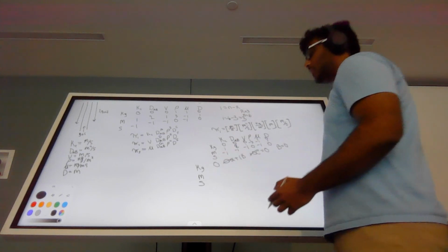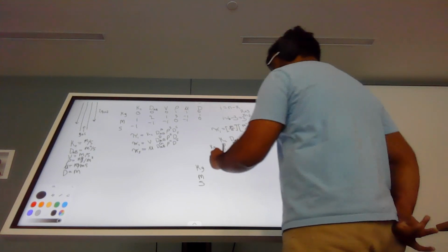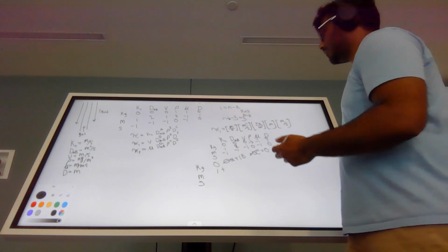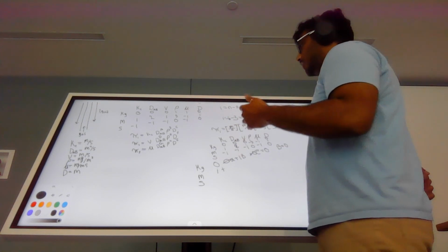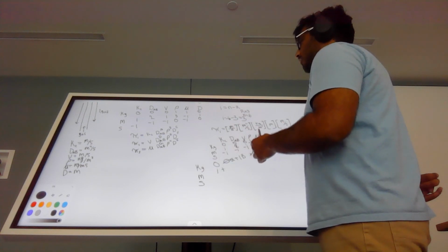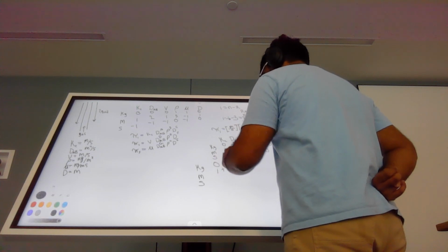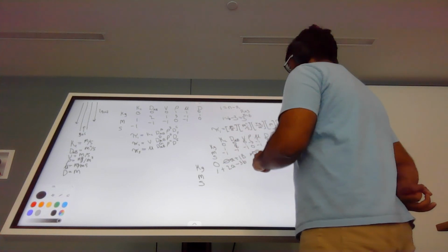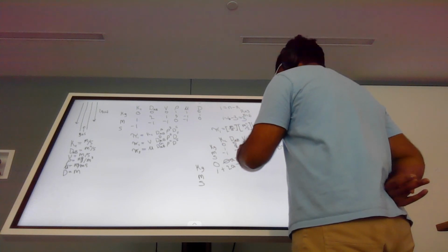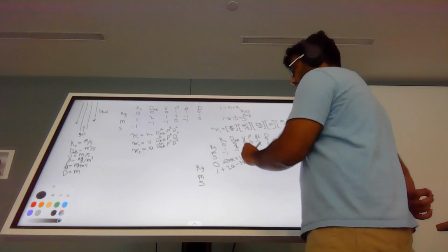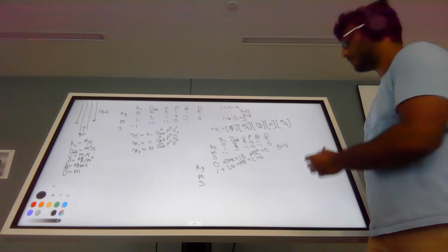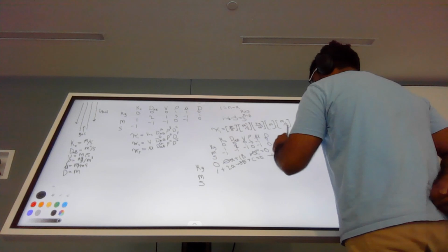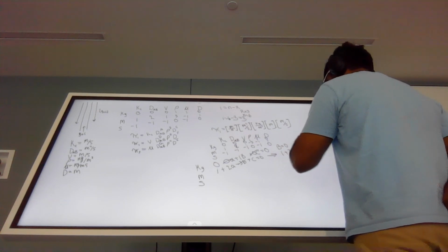So now we're going to analyze the meters within the units. So it's going to be 1, because that's our isolated variable, and we're not raising that to any power within our pi group. So since there's 1 meter in the numerator, we're just going to write 1. And then for our mass diffusivity, it's going to be 2A. And then for our density, it's going to be minus 3B. And then for our diameter, it's going to be plus C equals 0. And we could go ahead and cancel out B because we already knew that B is equal to 0. So that leaves us to the equation 1 plus 2A plus C equals 0.